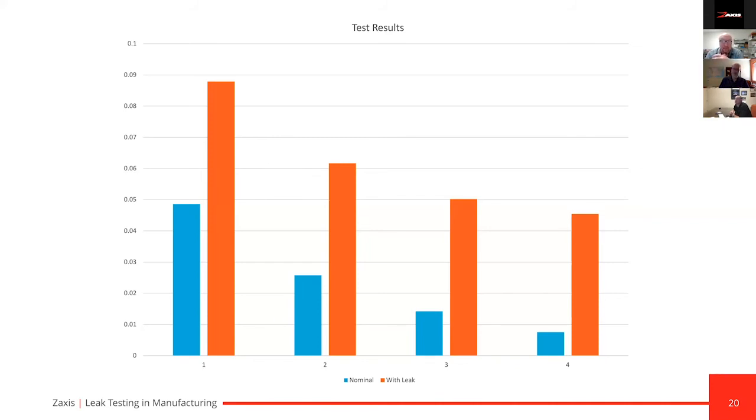And you can prove that on any product, any part, simply by running the part 3 times back to back to back. You will get reduced decays. But if you're trying to do some setup and/or some repeatability testing, what we usually recommend is having multiple parts to test. But if you don't have that many parts, we recommend waiting at least 2 minutes. So remove the part from being tested and let it sit for 2 minutes.